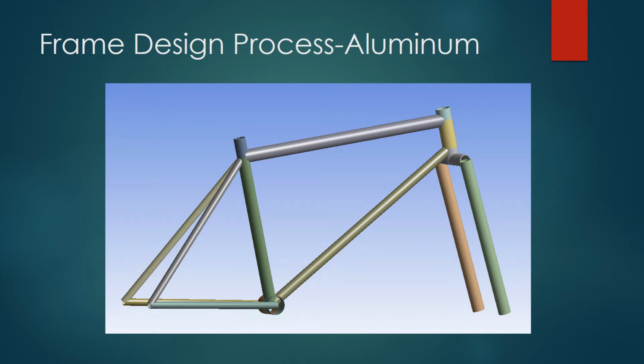The same iterative process was used to design the frame cross sections as steel. All wall thicknesses increased on the steer tube, fork, seat post, and top tube, and the outer diameter was increased as well. The final frame mass came out as 2.7 pounds with a fork weight of 1.28.